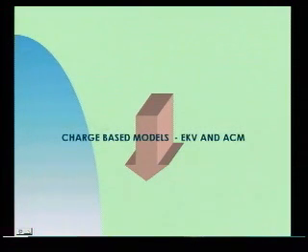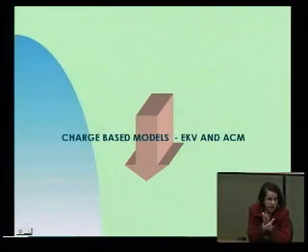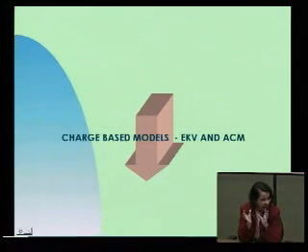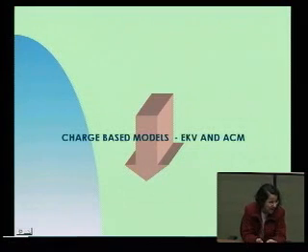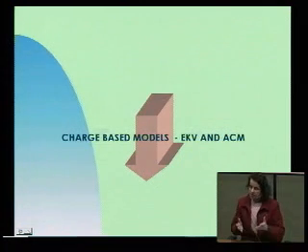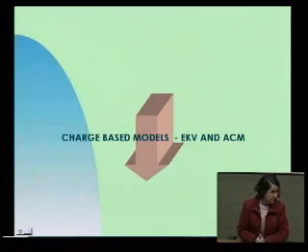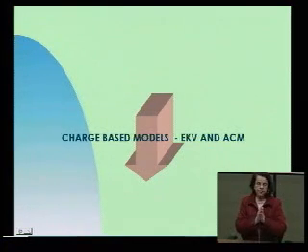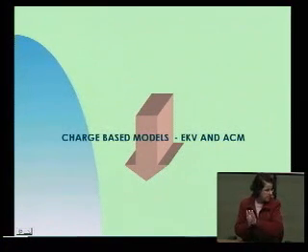Okay? Both are charge-based models, that is, they are derived from the charge density equations. That's why I put so much time in talking about the distribution of charge in the MOSFET, the semiconductor. Both are bulk referenced models, and both are single equation models.